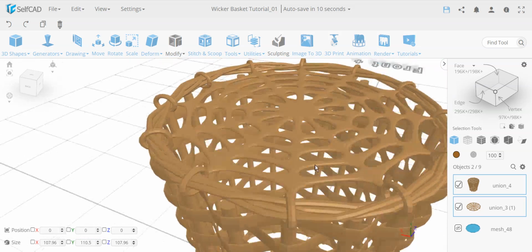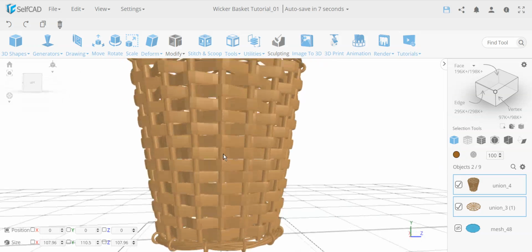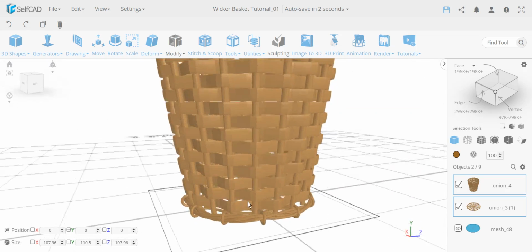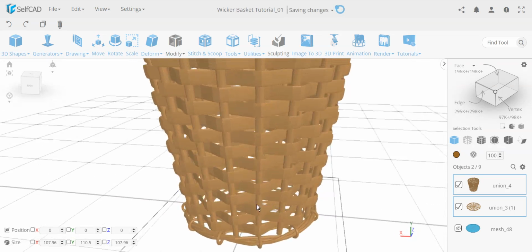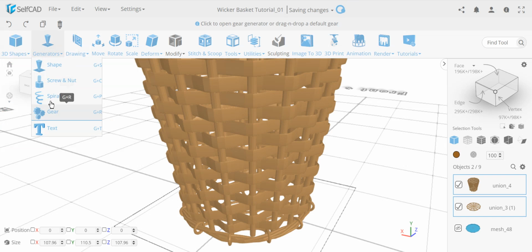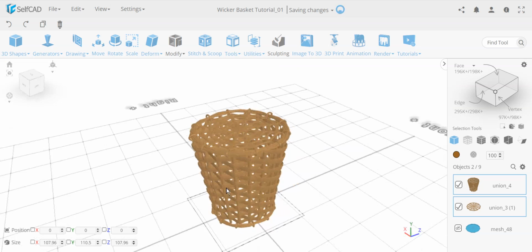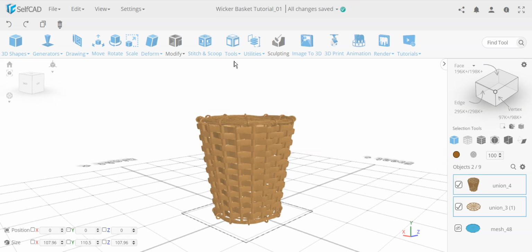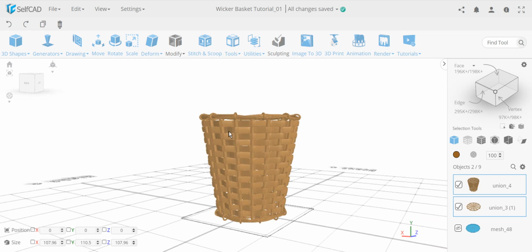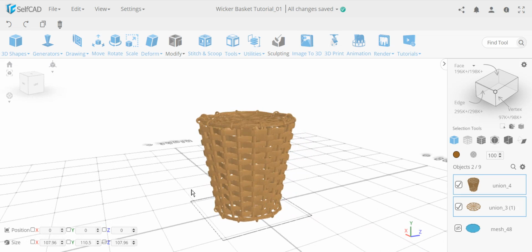So just to repeat what we have over here, almost the entire thing was used, first of all, creating some basic shapes: cylinders, circles, ellipses, and torus. The only thing we used a little bit more creating was the spiral, the thinned out spiral. Then the majority of the work used repetitive motions, which is copy offset, an inset to repeat, the option to repeat, the macro to repeat. And then it used a few options on follow path. It used follow path to extrude something around, to bend something around, wrap around, and to copy around.